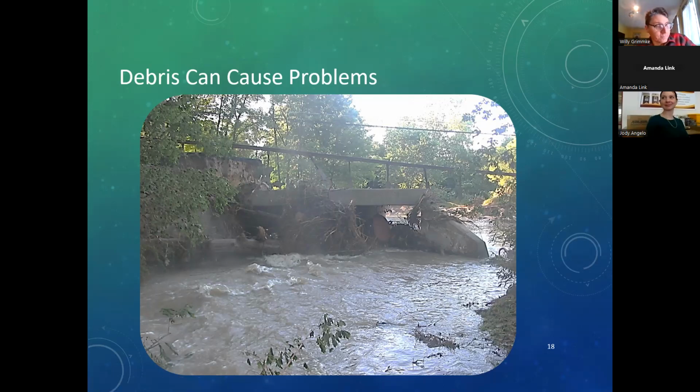And what that resulted in was having to come through and restore the road. There was some undermining as a result of this event, and the state came in on an emergency contract, grouted it up, and restabilized it. But keeping debris out of your culverts is critical for long-term performance of the culvert and the embankment.